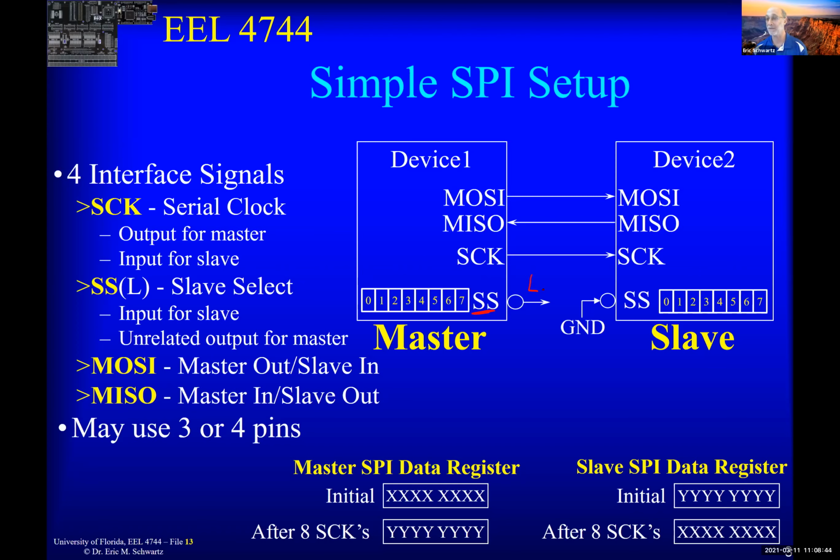All pins by default are inputs. And so if there's an input pin that you're not using, remember, when something gets nearby, it can make it go low. It could make it go high if it's not being forced to be any particular value. So if you're going to leave this an input, then what you typically do is put a pull-up resistor on it. So if there's nothing else connected to it, it's high. And if something else is connected to it, it can bring it down to low.